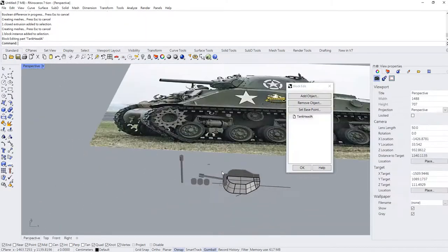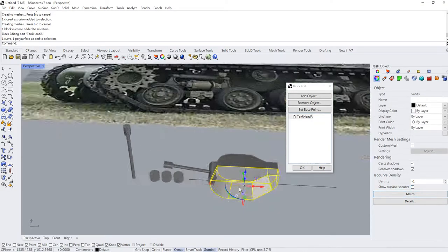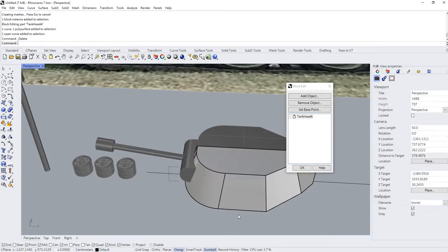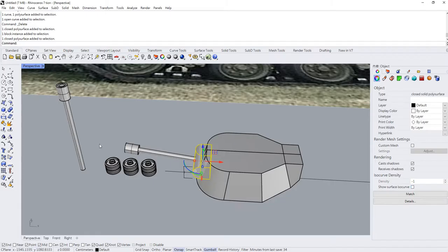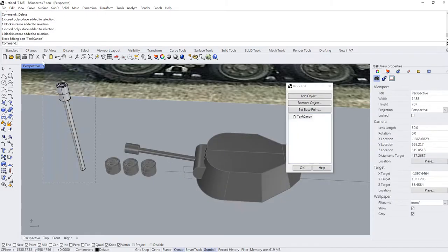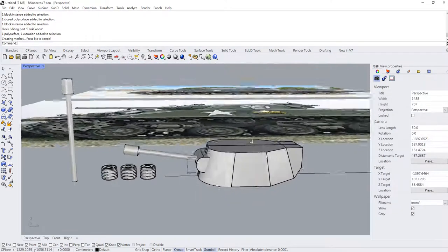Let's try to clean up this area so that we hide the iso curve and also delete the useless curve for this part as well. Yes, hide the iso curve. Remember, if you want to hide the iso curve of the block, you have to double click, enter the block editing mode, and uncheck the show surface iso curve. Click OK, and it will be done.